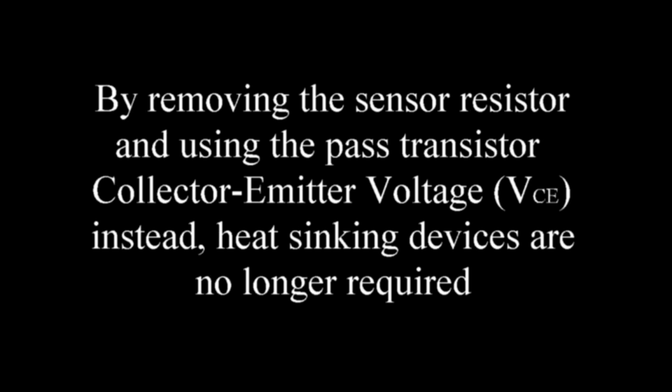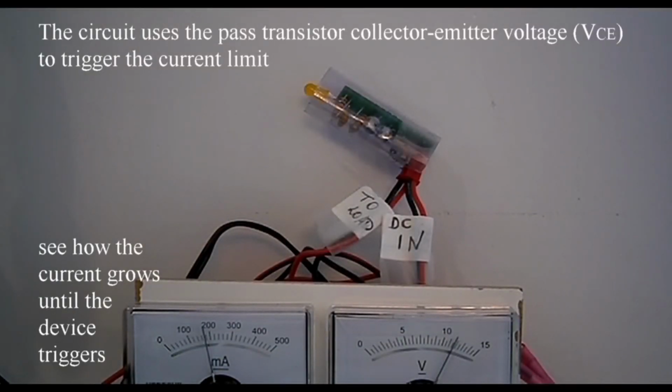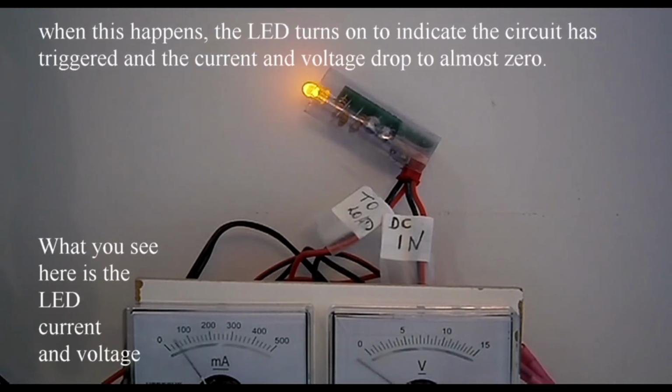Current limiting circuits. Part 3. In the first video of this series, current limiting circuit breaker, I presented an alternate design to limit current in a circuit and protect it against short circuit by removing the sensor resistor and using the pass transistor collector emitter voltage VCE instead. Heat sinking devices are no longer required. The circuit uses the pass transistor collector emitter voltage VCE to trigger the current limit. When this happens, the LED turns on, indicating the circuit has triggered and the current and voltage drop to almost zero. What you see once the circuit triggers is the LED current and voltage.